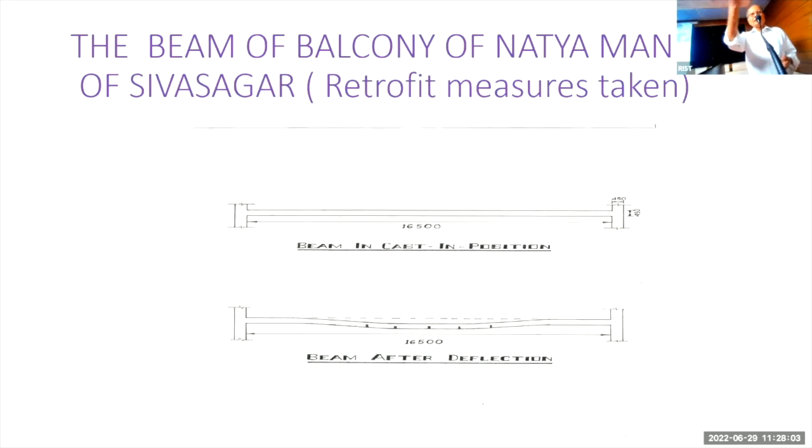By seeing this one, that's why I tell my students also, you can go for innovative measures on a particular aspect only and only when you have clear control over the basic knowledge required. So my advice here to my dear students, you give stress on understanding the fundamentals of engineering. So here, I designed on the basis of that. My fundamental concept I used here, I wanted to reduce the span, because I didn't want to dismantle the beam. I wanted to reduce the span so that the span to depth ratio is satisfied.